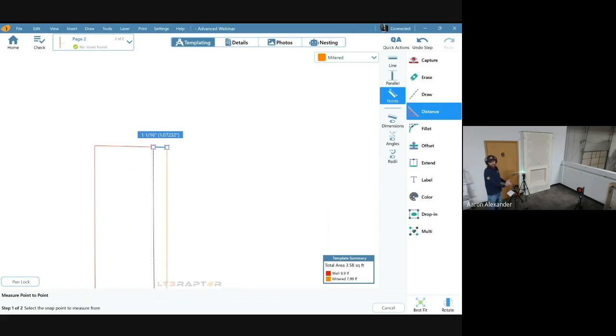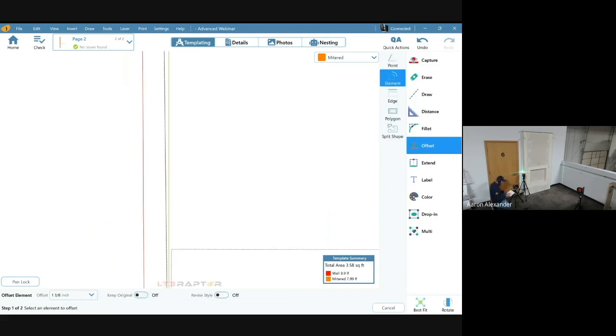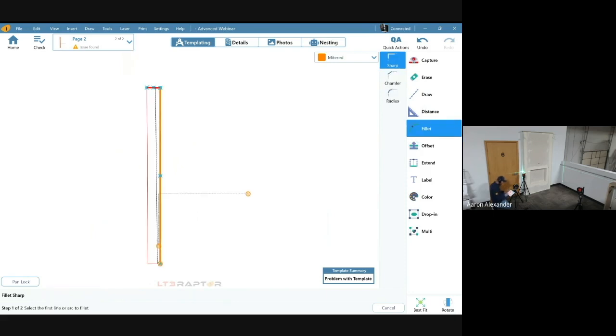So this is showing us how we got to cut the front edge of the return to match how we install the face plumb, right? Okay. So that's how we're going to plumb up this edge. Now, again, we do material thickness, that kind of thing. So we could go in here and do our offset of that orange edge out front. There we are. That's material thickness plus thin set. Then we fillet that together.